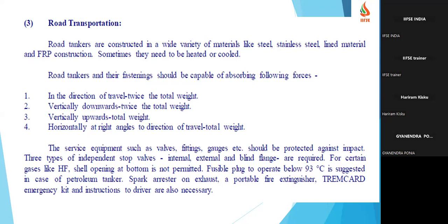In the direction of travel, twice the total weight; vertically downwards twice the total weight; vertically upwards the total weight of the vehicle; and horizontally at right angles to the direction of travel the total weight.